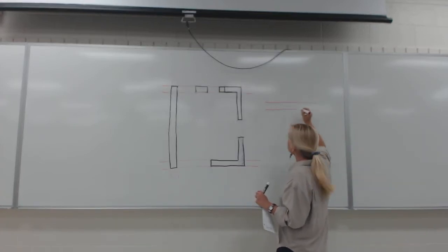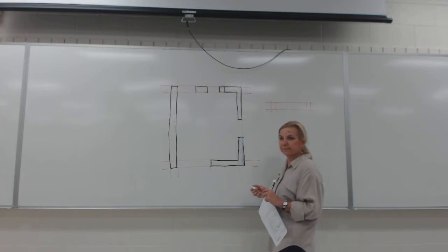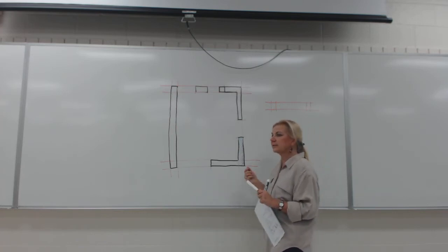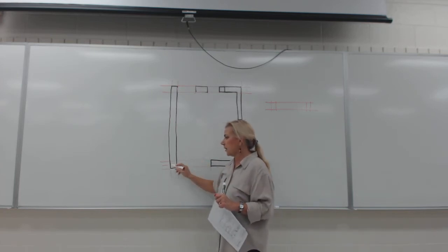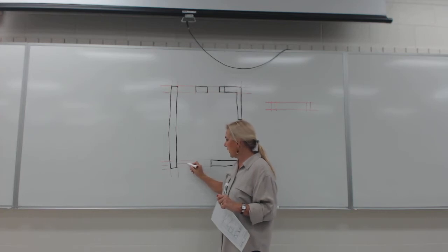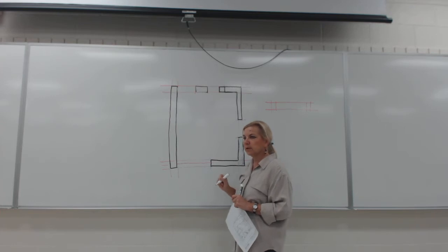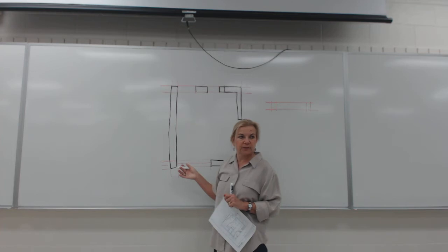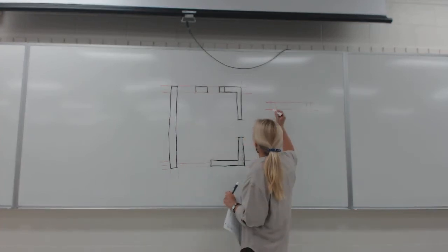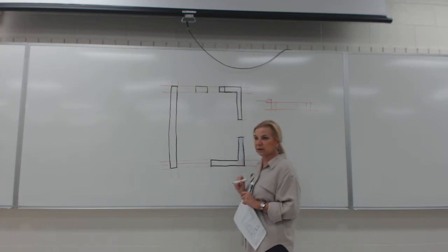It has 2 construction lines, and it has a 2x4 frame. Okay? So you would have to decide, and on most standard construction, our walls are 8 inches. If you draw a line halfway through, you'll be good, because most windows will be 4 inches. And most windows will be installed flush to the outside because the window frame comes with the trim for exterior siding. So if you draw it like this for starters, we're good.